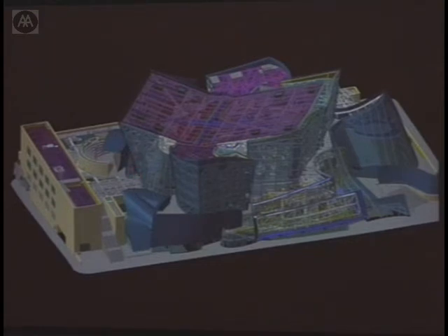And that's basically a zone. And the zone between the surface, it's a NURB surface of some sort, and what it is I'll tell you in a minute. But basically, it's an infinitely thin surface. It doesn't have a structure, and there's sort of a zone between that and the actual steel, which now has to contain, or gives you a space for operating and building a subsystem that supports the whole cladding. So you give that as a kind of microscopic design-build contract to the fabricator, in this case Parametric, who are of course amazing at this, and they came up with sort of the solution collaboratively with the office.